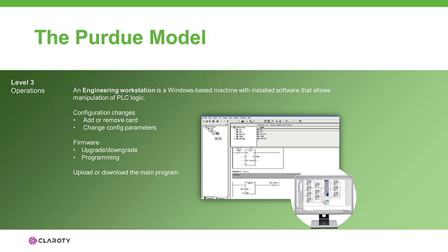Protection starts to become really important at this stage, because if an engineering workstation with extensive access privileges is compromised, an attacker can make low-level changes to PLCs. Without specialized tools, changes done at this level can be very hard to identify as a threat. For example, an attacker could use an engineering workstation to program an electric motor to operate at a higher speed, but could also program the HMI connected to the motor to show a normal operating speed.